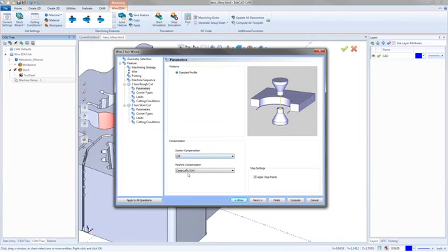But right down here, we have our compensation. There are two forms of compensation for your wire EDM, just like there is for your milling. You have system compensation, which is us taking care of the compensation for you. You also have machine compensation. That is going to be the compensation at your machine. You'll be able to actually comp the wire there. So primarily with wire, you're using one or the other. Either you're using our system compensation and you're letting us offset the wire, in this case 5 thou we need to move over, or you're going to do it at the machine. It's just whichever one you want.